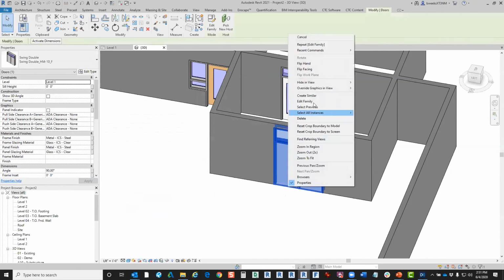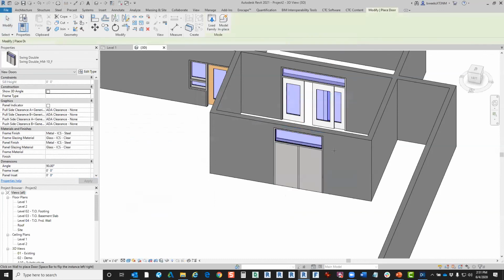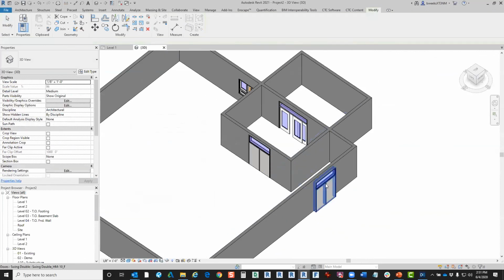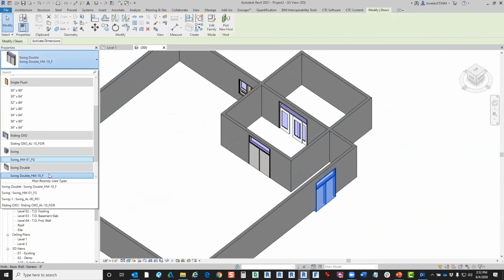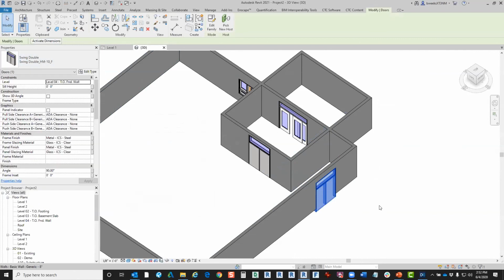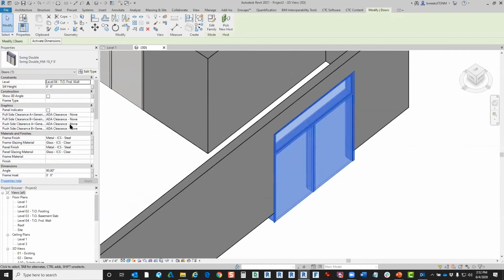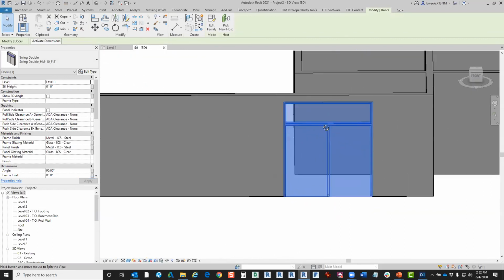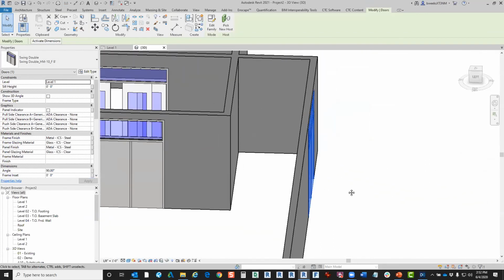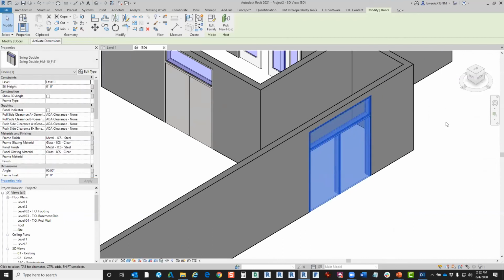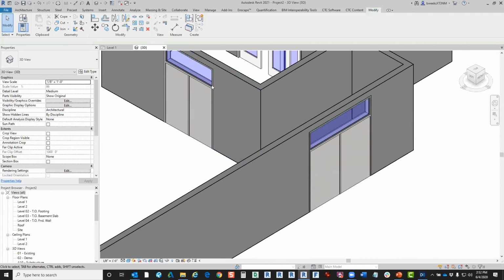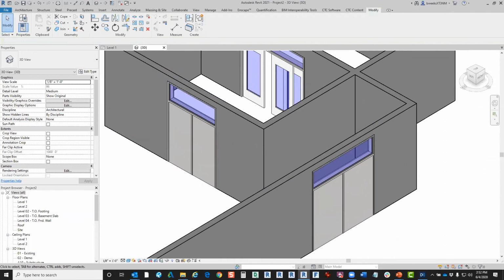I'm going to duplicate it, and then change that to my F8, which is now a different family type, I should say. It keeps putting it on a weird level. But now I've got my 8-foot door versus a 6-foot, and it's utilizing the same standards that I set. Maybe the materials are similar to what I set up in the configurator.